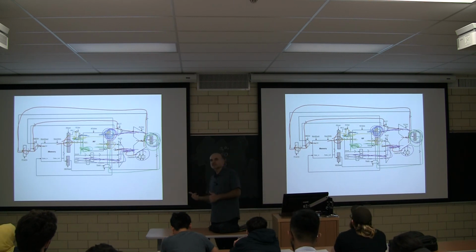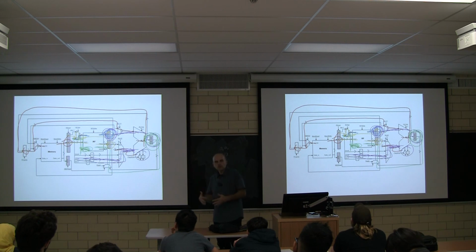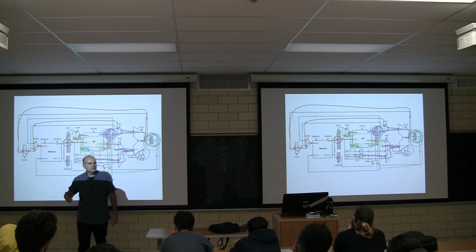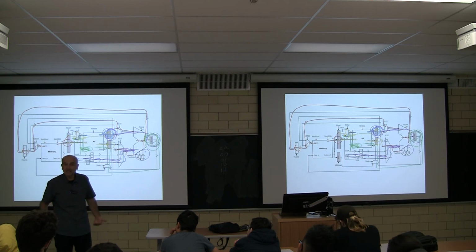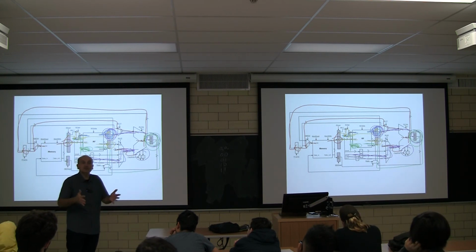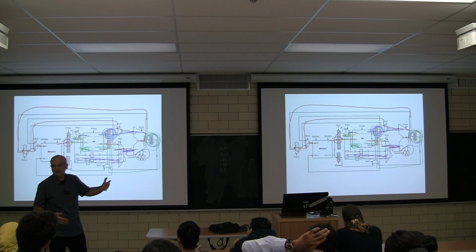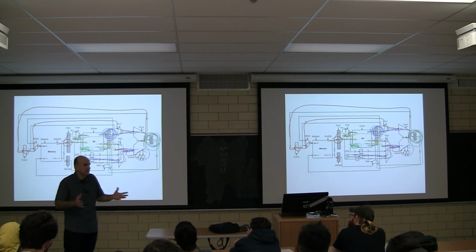Could you make this take 4 cycles? It's a trick question. In cycle 2, you have a choice. You can speculate that the most useful thing to do is to take the upper 4 bits from the instruction opcode and use that as names. Or you can say, how about I read R1? Because I think that's the most important thing. If ORI was the one designing the machine, that's what it would do. Right? I want to be faster. In that case, ORI will take 4 cycles because the speculation you did in cycle 2 turned out to be the right thing. Add, NAND, subtract, potentially shift will take more cycles because you haven't read the right registers. Fair enough?